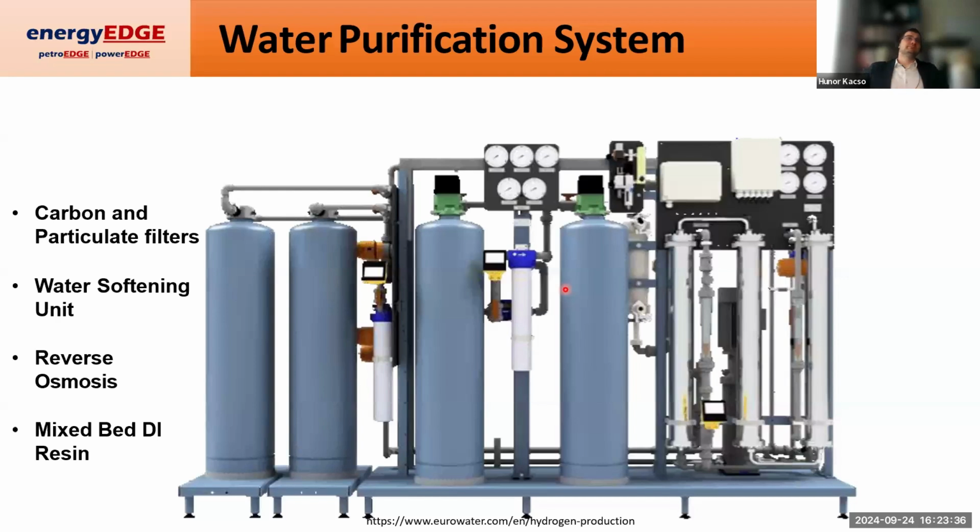In short, the water purification system is a carbon and a particulate filter, and there'll be an element of water softening, and there'll be reverse osmosis. And after the reverse osmosis, we'll see the conductivity of the water drastically reduce, but not quite enough for PEM electrolysis.